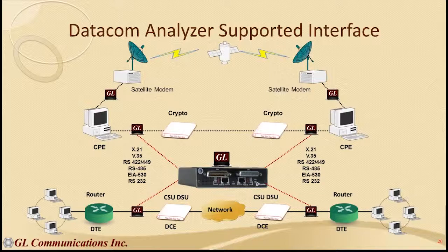So the telecom rates are very discontinuous. You jump from 64 kilobits to 1.5 megabits. Well, that's a big jump. And then you jump from 1.5 megabits to a T3, which is 45, or the E3, which is 34 megabits. Or the next jump up is even much higher. But in the satellite world and in the data communications world, you want finer gradations.